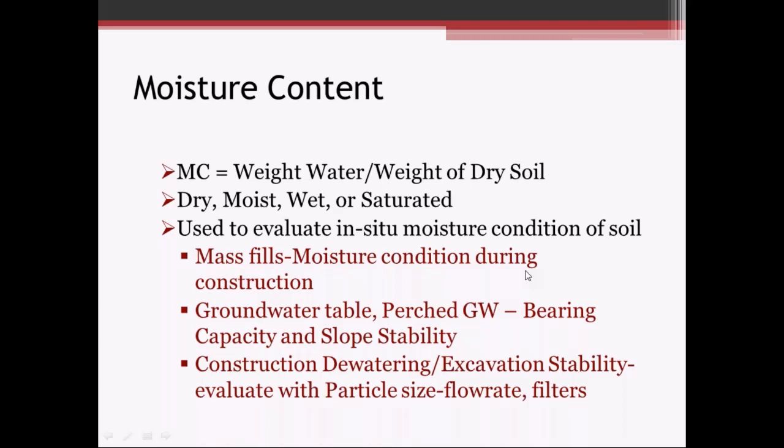For construction dewatering, we can perform particle size analysis in the water-bearing layer. And from that information, an appropriate filter system can be designed for the construction dewatering, which could consist of simply a geotextile or some sort of granular filter material.